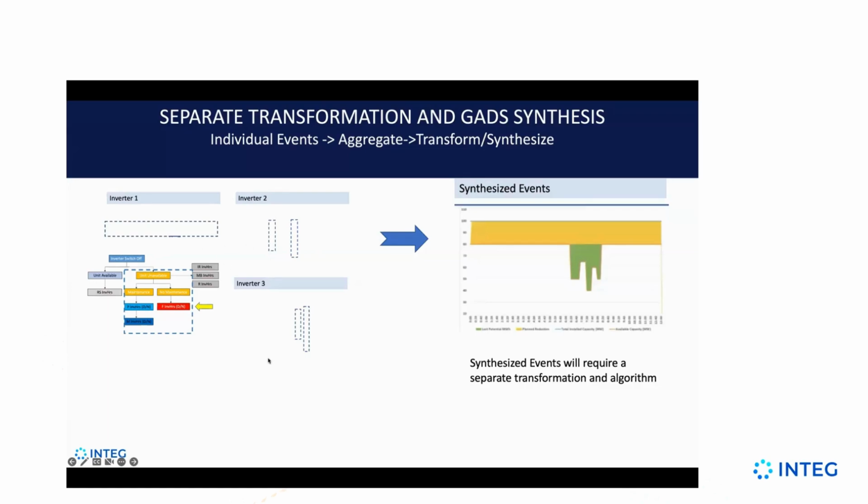Now, remember, these outages are full outages. If you have an inverter partially out, NERC doesn't care. Throw that out for this point. If the inverter is out, if it cannot produce, not because of lack of sun or irradiance, or low wind or high wind, but because it's not functioning, or you're in a planned or maintenance outage, then you are going to count that.